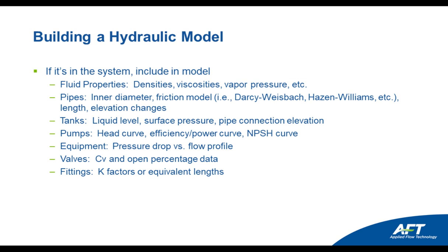Other things that are important to include: for your tanks or reservoirs, your liquid levels and service pressures will provide a pressure coming into the piping, and so it's important to specify those properly. During a transient simulation, your liquid levels could change. That would be important to account for.